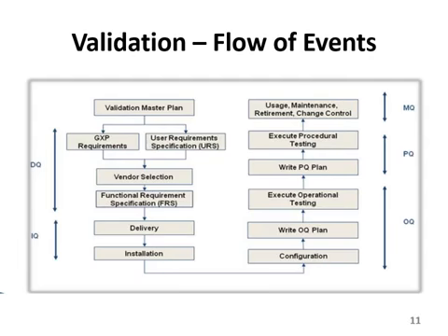Execute operational testing. Now you have written the operational qualification plan, and now test it, that is, is it working? If it is working, excellent. If it's not working, you need some changes, do the changes. Then the performance qualification, PQ, write the PQ plan, how to perform on the machine. Execute procedural testing, then again test it.